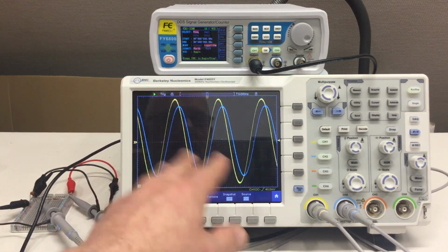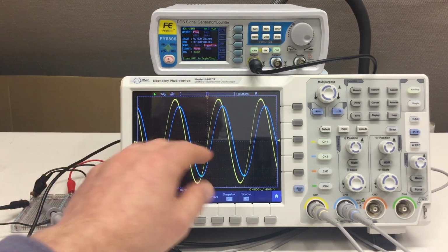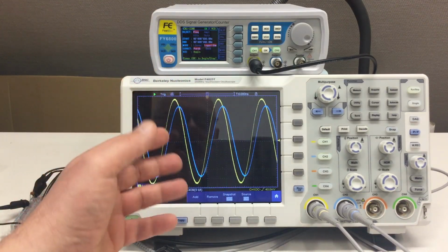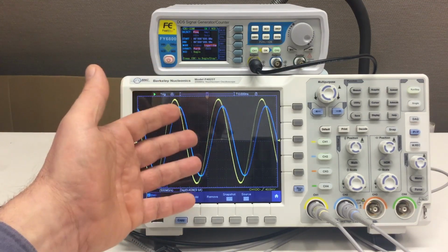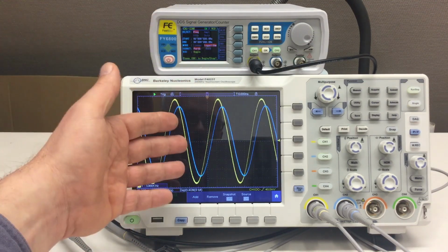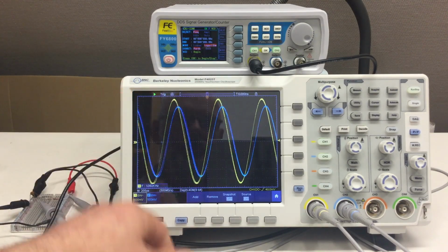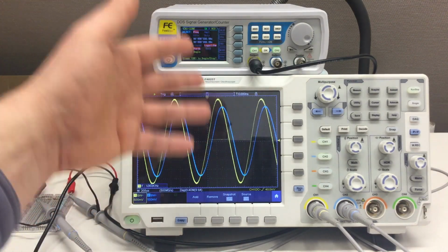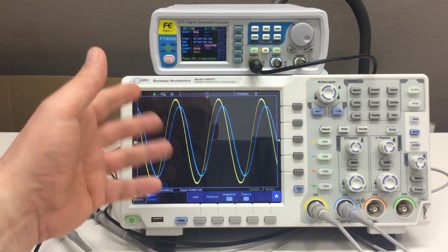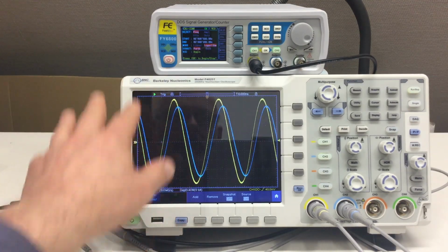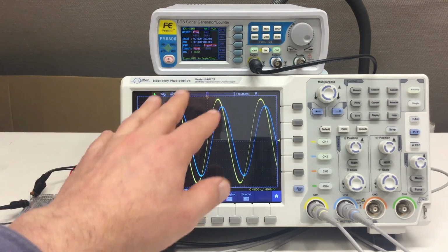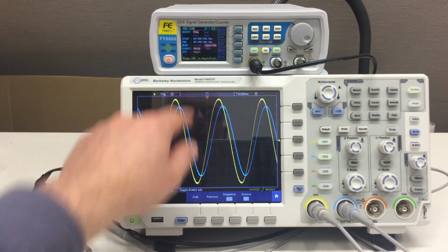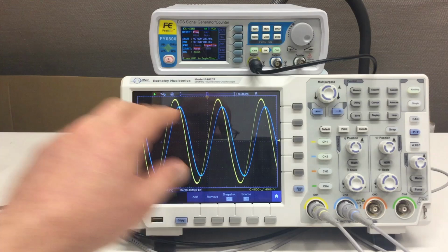I don't know if this is some offset voltages in the analog part, or if the reference of the analog to digital converter, which must be in here somewhere for the VCO input, is off. I really don't know, but we need to keep in mind that even the start and the stop frequency are not necessarily those which we set in the device.